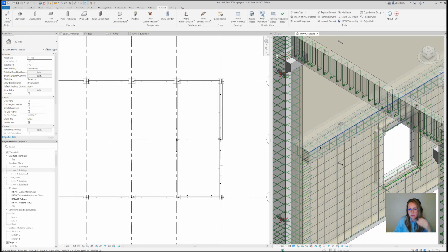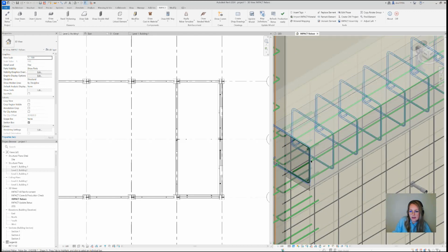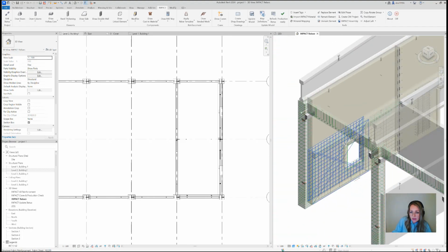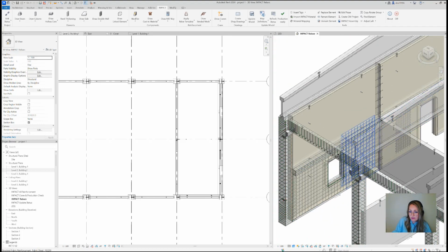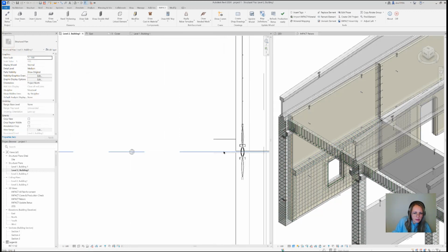Yes. So with the help of the templates, once you draw such rebars on a panel thickening, you can reuse it. It just needs to be the same family, not the same type, but the same family. You can have several types within the family, and we're going to adjust it according to the constraints. So rebar templates, a very powerful tool. With just several clicks, you can see we can add the rebars, right?